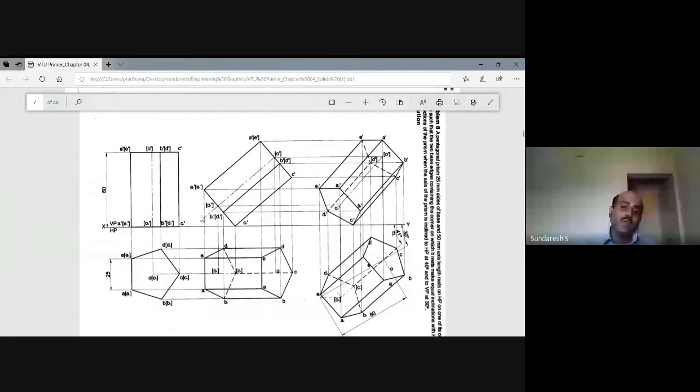So this is what you can show, and after completing all the lines, you have to extend the axis line till the HP, and you can show that the axis is inclined 40 degrees with respect to HP. That is what we want. Don't show here the C dash and C1 dash. Only O dash and O1 dash should be shown there. Okay. So this is the initial position, second position front view representing the axis inclined to HP at 40.